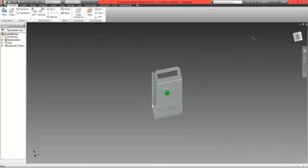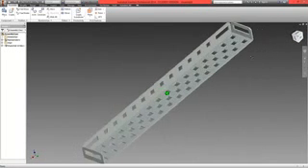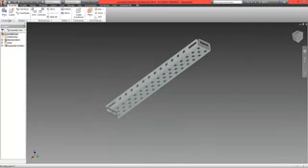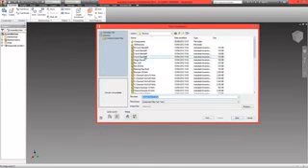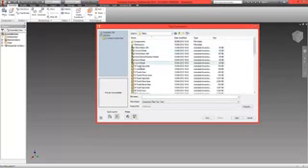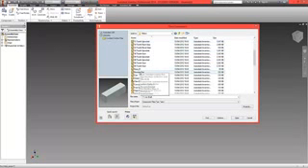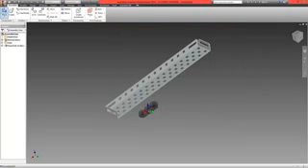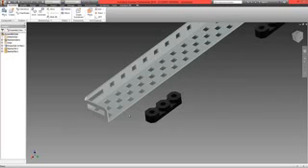This is our first side chassis part. So from the ribbon select the free rotate tool and rotate this part around. What you can now do is place the bearings, so choose place, and if we move up the folders to the motion folder, within that we should find a bearing flat which looks like this. Open up, and I'm going to create two of these, 1, 2. Right click and select OK.